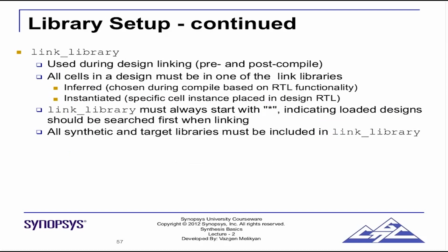Link library is used during linking, pre and post compile. All the cells in the design must be in one of the link libraries. Inferred cells means whatever design compiler used to implement from the target library. Let's say your design has a PLL. Now PLL is not a cell which design compiler will use to implement anything. PLL is a very specific cell. It generates a clock. So you will instantiate a PLL in your design.